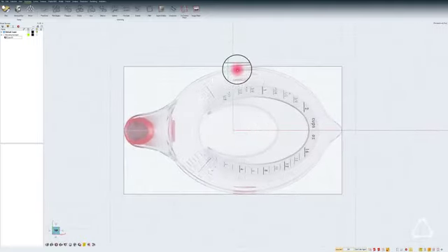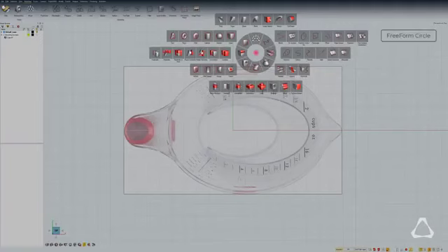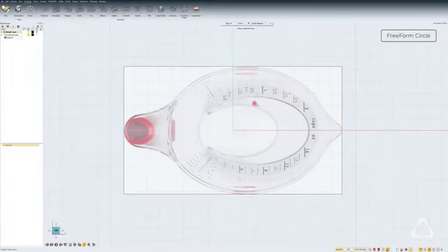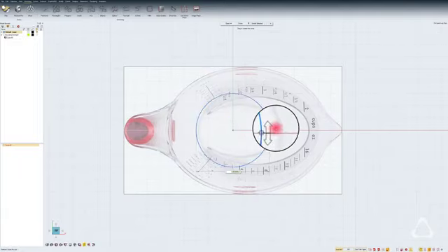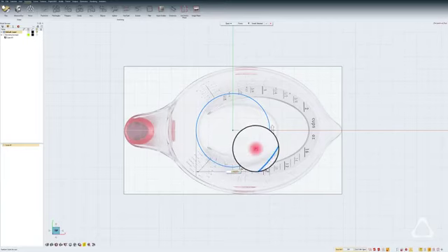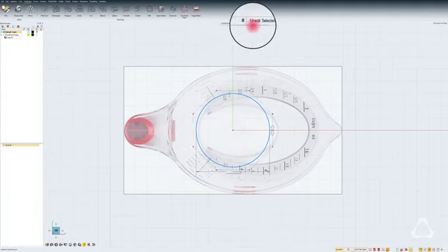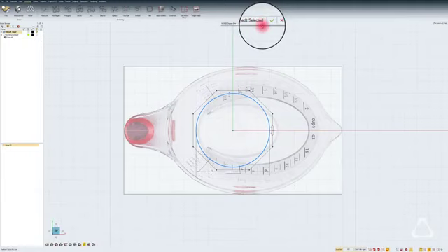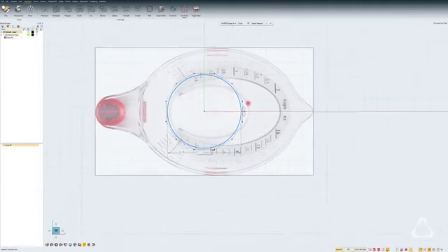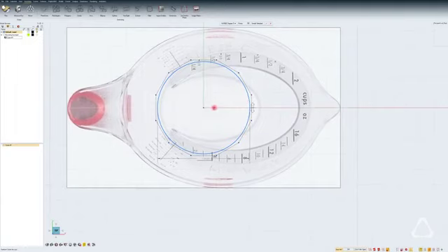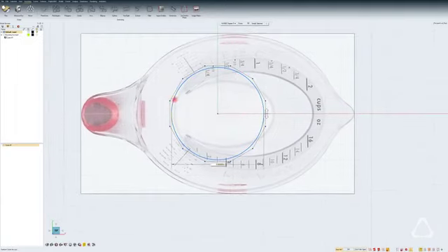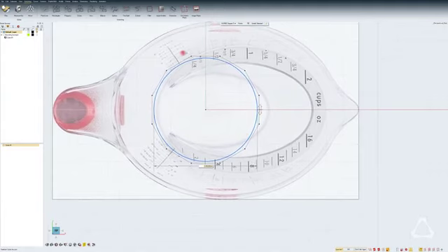So the first curve we need is just a basic circle. So alt right click and select the freeform circle tool and click in the center and just create a circle for the time being. Now in the guide bar, for the exact option, change it to NURBS degree 3 or 5, doesn't matter, and we can keep it at 8 points, or for this let's make it 12. Now this gives us more points to edit, clicking the circle, and start moving the points as we need.